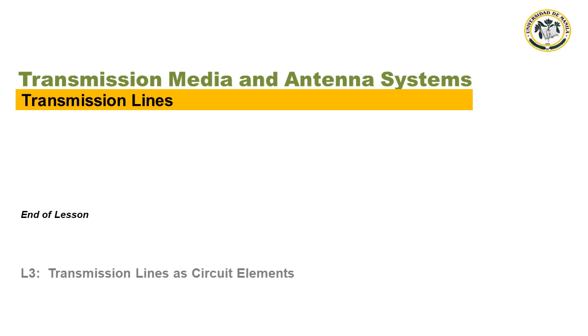We've touched on how to apply this concept in making a reactive circuit out of a 50 ohm line. And there are also special transmission lines called microstrip and strip line, which can be used as tuned circuits, filters, phase shifters, reactive components, and impedance matching circuits.